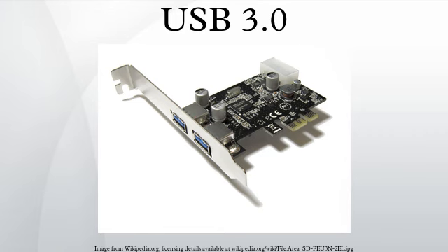Architecture and features. In USB 3.0, dual-bus architecture is used to allow both USB 2.0 and USB 3.0 operations to take place simultaneously, thus providing backward compatibility. Connections are such that they also permit forward compatibility, that is, running USB 3.0 devices on USB 2.0 ports. The structural topology is the same, consisting of a tiered star topology with a root hub at level 0 and hubs at lower levels to provide bus connectivity to devices.